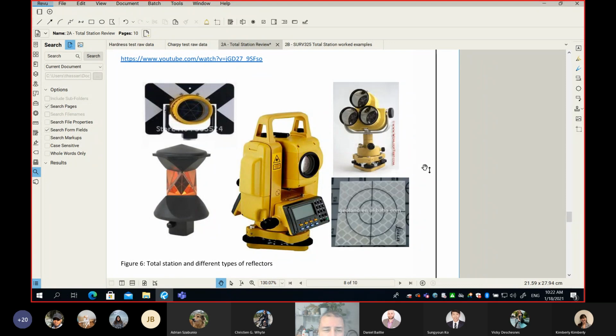Okay, so maybe for the purpose of the exercise, I know some teachers measure the traverse with a rod, but I can tell you, if you want the highest precision, then for the traverse you would use the assembly on the right, and not necessarily a three-prism one. It's even a single prism on top of a tribrach on top of a tripod. Okay, so that is really what I want to emphasize and get you to understand. Now let's move on to our next prism, which is the bottom left.